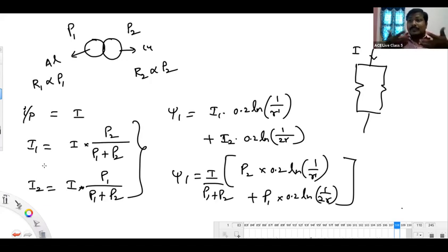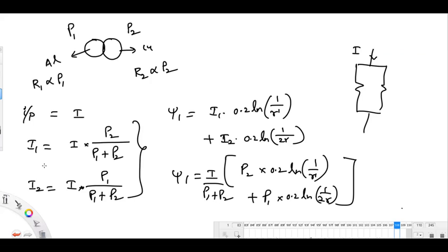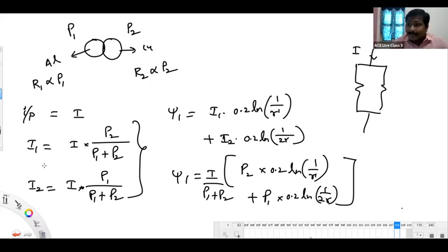So the generator has to supply reactive power. What is that statement? The generator should supply what the load asks. To create magnetic flux, are you supplying reactive power? No, it is demanding. It's demanding some reactive current. That's why the generator has to supply it.